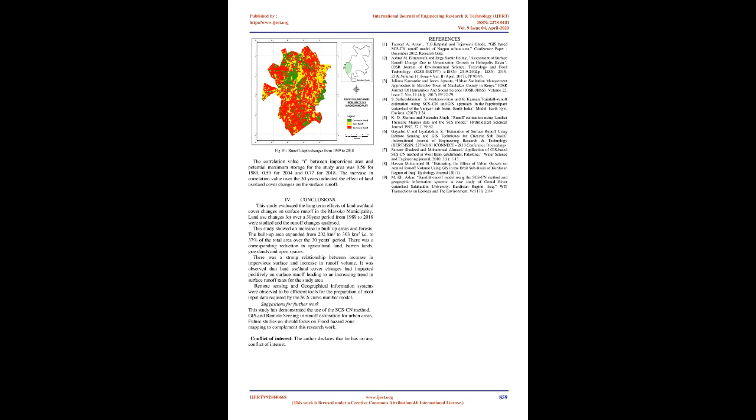In order to illustrate the change in runoff production over the 30 years, the raster layer of runoff depth values for 2018 was divided with the layer of runoff depth values for 1989. The obtained results were classified into 3 categories, namely, less than 1 representing decrease in runoff volume, no change which represents the same or unchanged runoff, and greater than 1 which represents increased runoff.